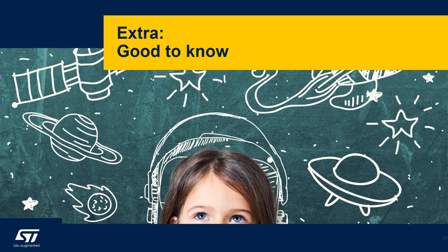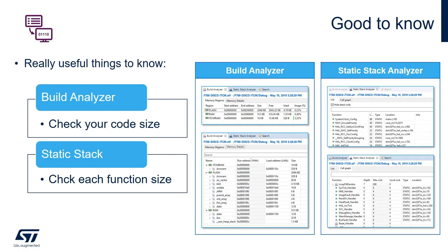A few extra pieces of good information that the IDE can provide are the footprint for the flash. We have the build analyzer and the static stack analyzer, which will give you an overview of the amount of footprint that your application is taking from Flash, from RAM, or from any linker file that you added on your own.